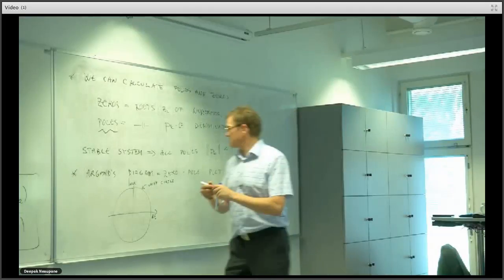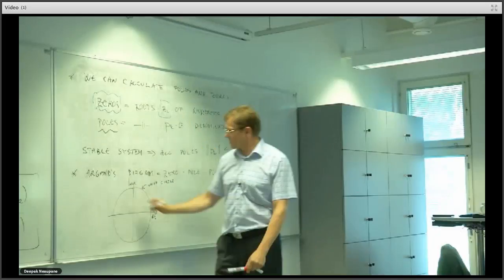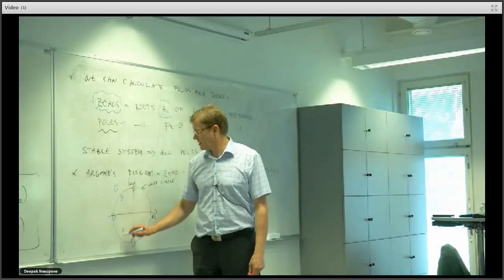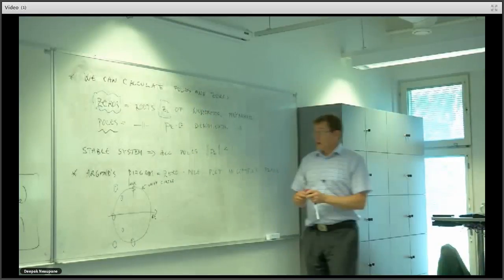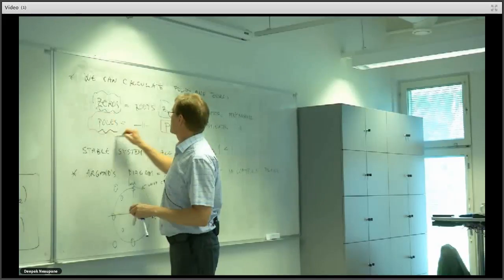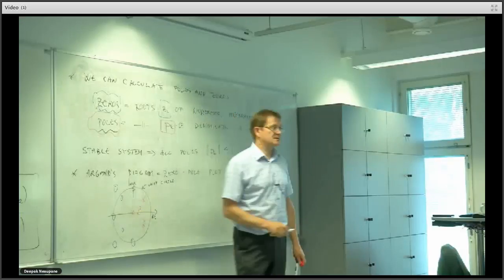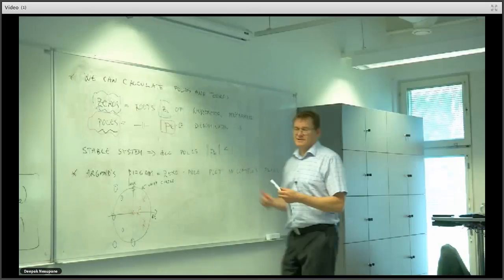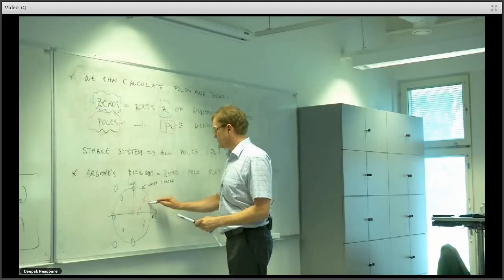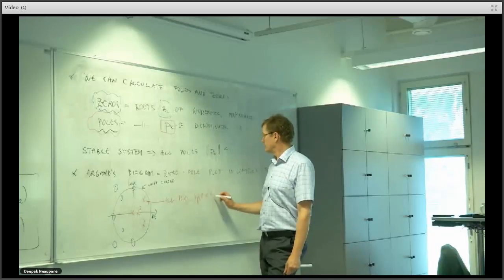We need those. So if our zeros would be the blue ones, sometimes they will be on the unit circle, sometimes not. They can also be something like that here, anywhere, but only so that you also have the complex conjugate pair. Then poles. Poles inside of the unit circle, maybe some multiple poles and even some poles at the origin. Just an example. So that would be a stable system.